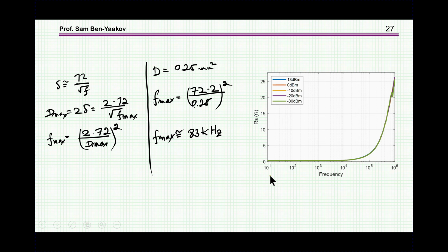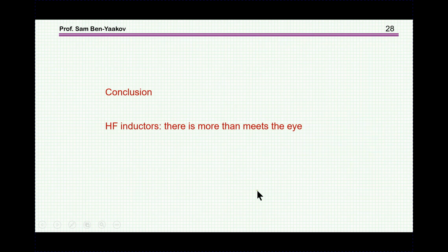Now, this information is very seldom given by a vendor or manufacturers of inductors. So this is something that if you really do want to do a good design, you do have to test and check yourself, because as I've said, this information usually is not found in datasheets.